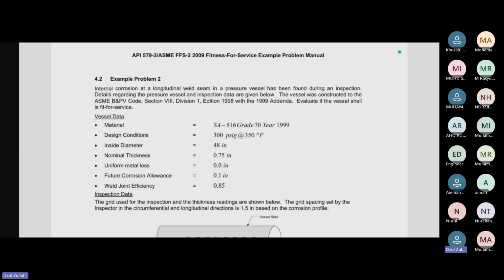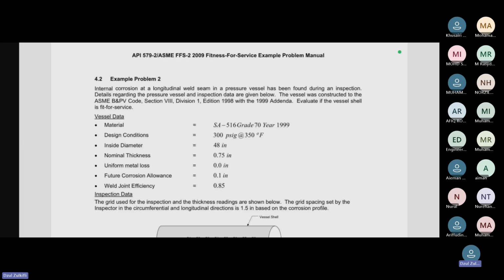There are other chapters in FFS, like dealing with brittle fracture, for example when you want to run your equipment colder than what it is designed for, or creep, which is if you run hotter than what it's designed for. There's FFS for cracks, too. If you have a crack, can you continue operation? Some of it is more advanced than others. But in my opinion, parts 4 and 5, regarding corrosion, erosion and wall loss, are very applicable across upstream and downstream. I will even say outside oil and gas also, I'm pretty sure this is quite applicable. So yeah. Next, what are part 4 and part 5?